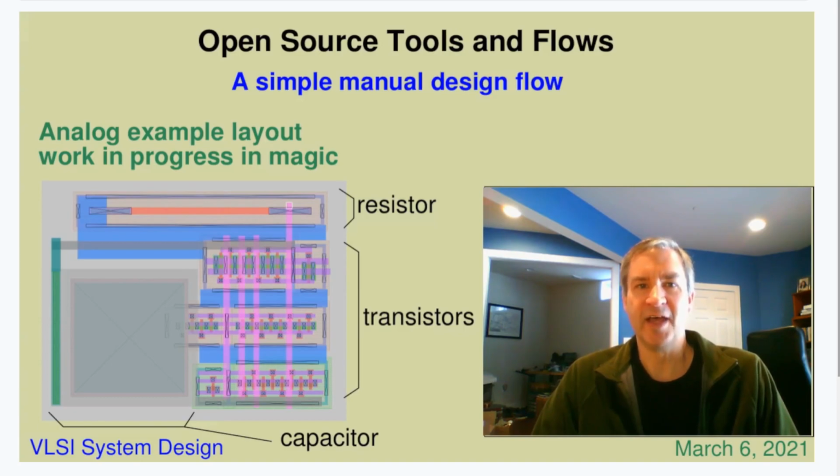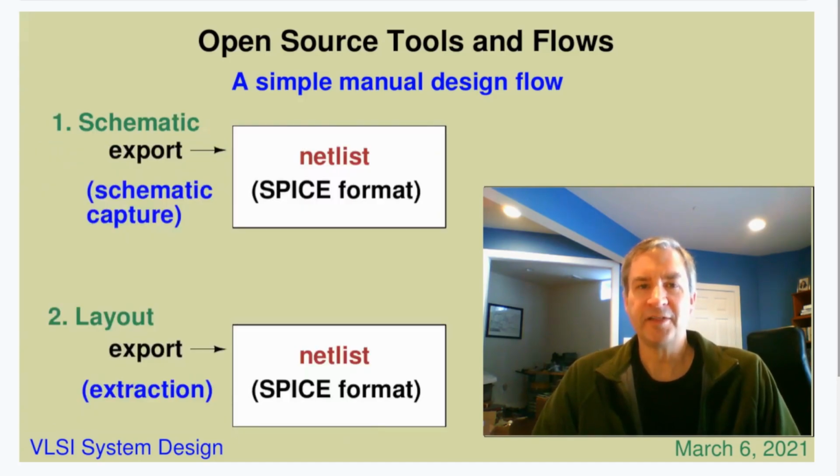Those are advanced topics of design, and I'll gloss over most of them to get to the part about physical verification. The final step will be to run LVS. Again, this will be covered in much more detail later in the next and in the last lecture and labs. LVS takes on a number of forms, but in this case we'll be doing the traditional one, which is comparing a layout to a schematic. Of course, a layout and a schematic are very different forms, so we will have to have a way to get them both into some common format so that we can compare them. That common format is the netlist, specifically the SPICE netlist. Better yet, we have open source tools that know how to deal with files that are ngSpice compatible, so we can verify with the same netlist that we simulate with.